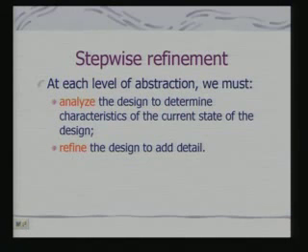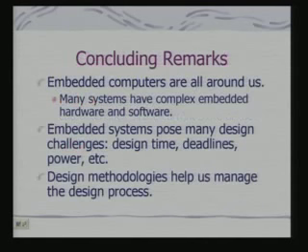I cannot really separate things out, because if I cannot meet a deadline using pure software on a general purpose microcontroller, I might need to design special purpose hardware for it. And that exactly leads us to what is known as software hardware co-design, software hardware partitioning, and those approaches. So, the stepwise refinement we are talking about is stepwise refinement of both hardware as well as software. And what does that mean? Stepwise refinement of the system as a whole.